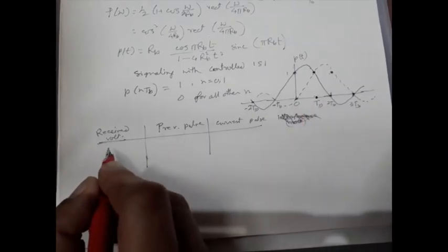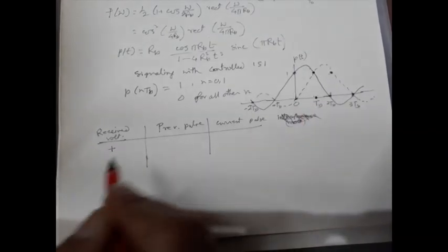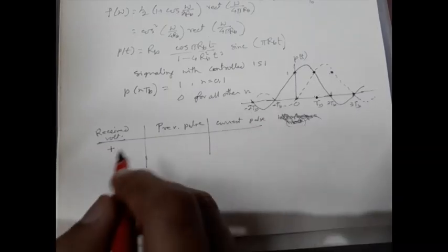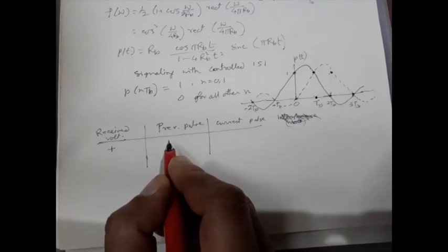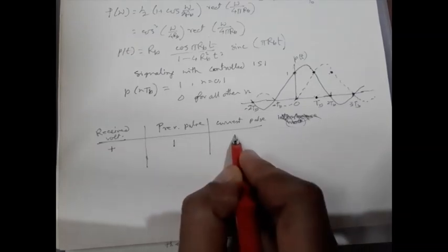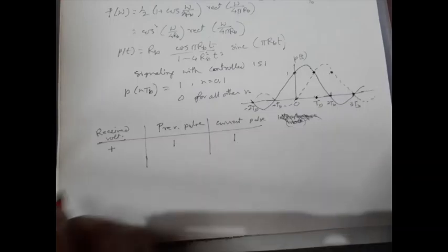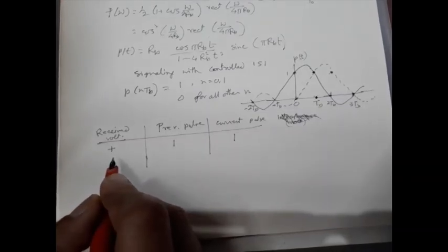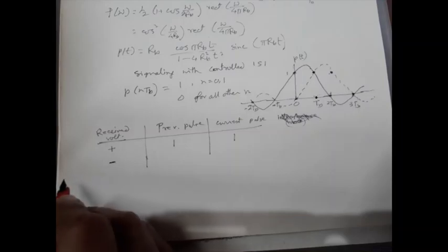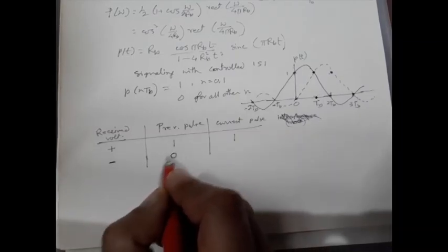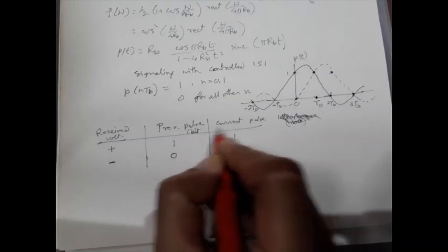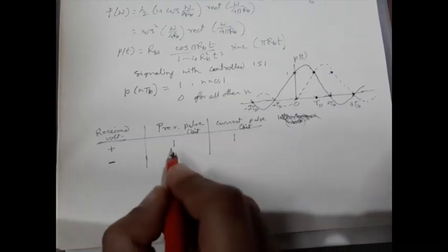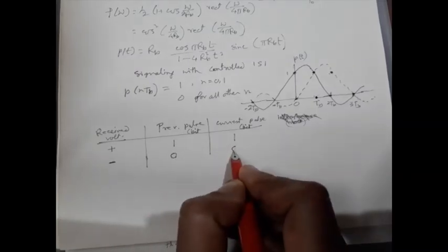So the received pulse is now sampled. So the sampled value is, say, a positive value, say +2. So our decision will be previous bit was 1, current bit is also 1. Now if we have received voltage negative, that means the previous bit value was 0, so the previous bit was 0 and the current bit is also 0.